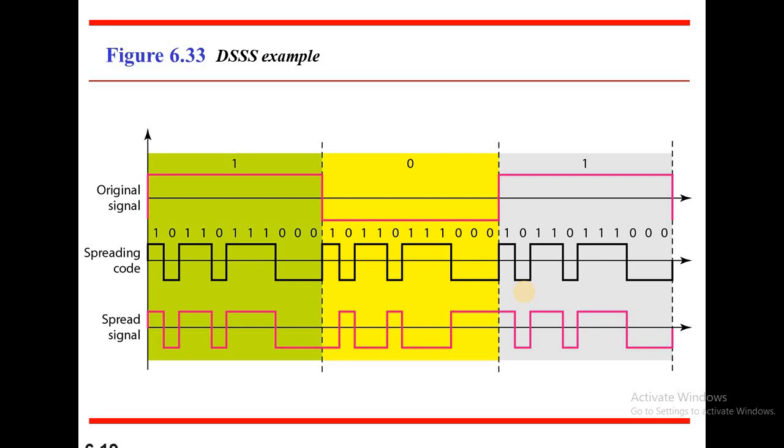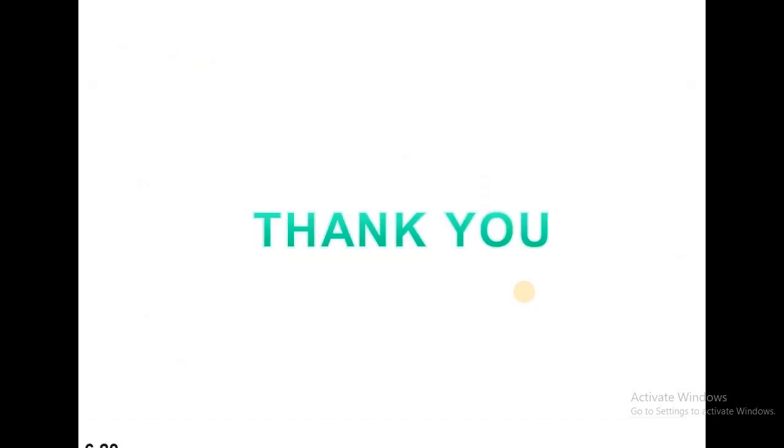What is the disadvantage of DSSS? With serial search acquisition, the time is very large, which makes it slow. The synchronization is affected by the variable distance between transmitter and receiver. The chipping sequence must have a high rate, and its length must be large enough to make the sequence truly random.